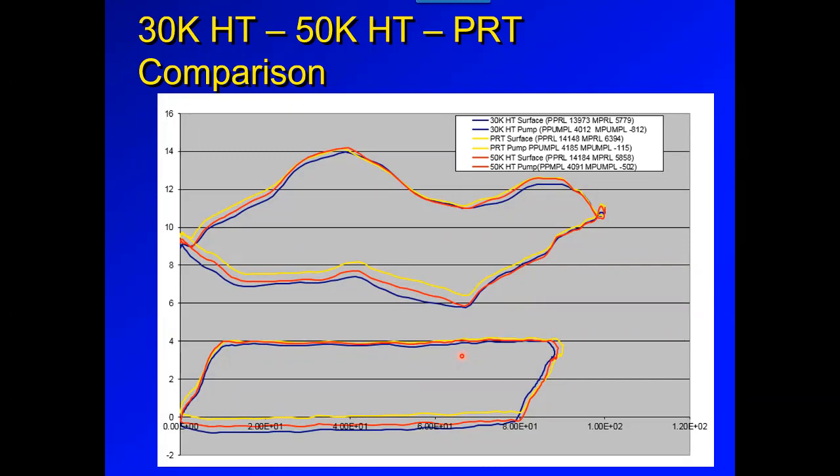One of the things I found, managing a team that utilized Echometer equipment to optimize and troubleshoot wells in the field, is that all the technicians were outfitted with PRTs. And I kept a 50K load cell back at the office so that if we lost pump action on a well, we could go out and run the 50K load cell to determine exactly what the issue was. But if the well was pumping, in routine operations, identifying circumstances like full pump, gas interference, fluid pound, traveling valves, or standing valve slippage, the PRT was giving me great data, accurate and safe for my analysts as they went through the field.